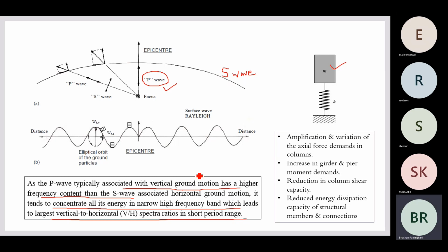And that is the reason the scale factor that has been mentioned, and the multiplication factor, will play a vital role in defining the function as well as the load case in the vertical earthquake case and in combination with the horizontal cases. So we should consider a three directional earthquake in seismic zones 4 and 5. In India or anywhere wherever the high seismic zones are, this is what should be considered.